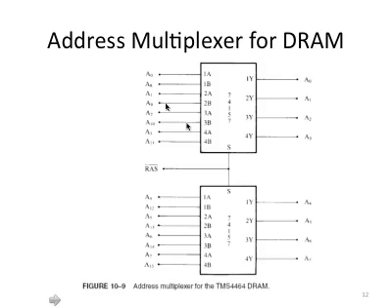So you are dividing this 16-bit address into two halves, based on the value of RAS. It's either A0, A1, all the way through A7, or A8, all the way through A15.